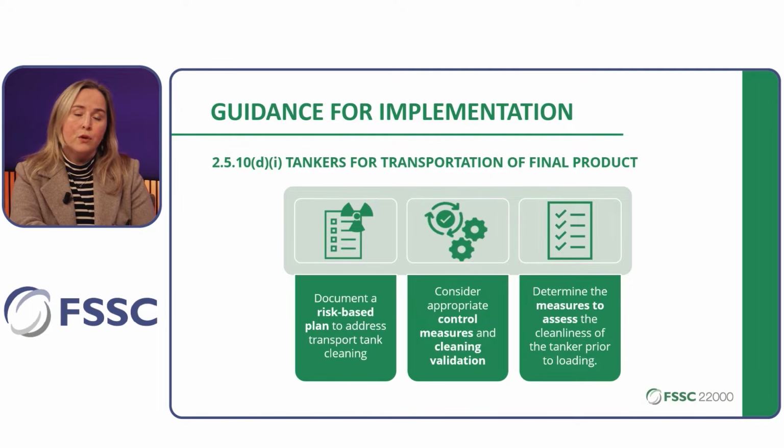So now getting a little bit deeper into this guidance document and looking at the guidance that is specifically included for 2510D1 to start off with. This is guidance for where organizations need to document a risk-based plan to address transport tank cleaning. So organizations need to start by conducting a risk assessment and ensure they consider the potential sources of cross-contamination when they undertake this risk assessment. So relevant hazards need to be assessed, and this could be physical, chemical, microbiological, or allergenic hazards, and the organization needs to make sure that they use a methodological approach when undertaking this risk assessment.